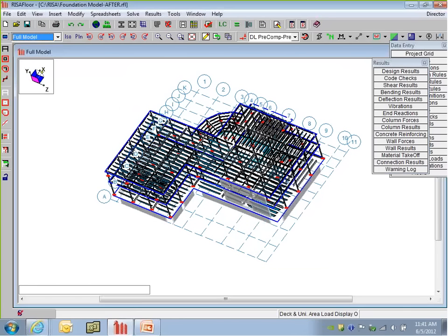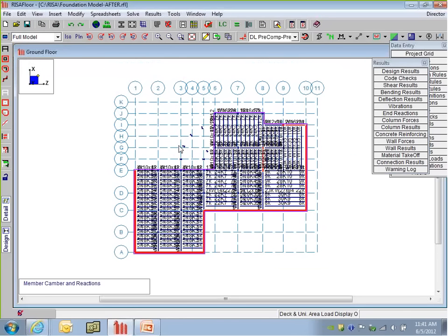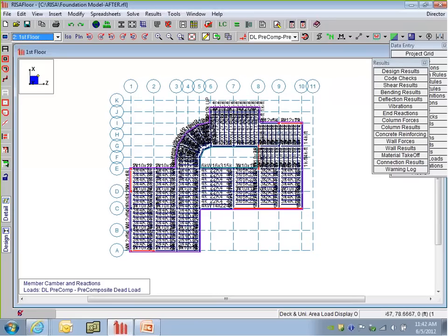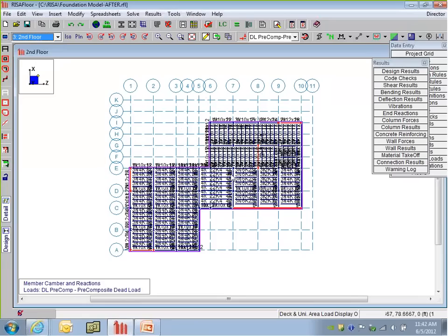When I was in design, a lot of times I used the basement walls as my shear walls, and then my upper floors kind of carried through in a smaller geometry. Just portions of that wall were used for lateral. I sprinkled in some moment and shear frames in here. Maybe you just stick with one type of material, but I figured I'd demonstrate a little bit of everything in here.